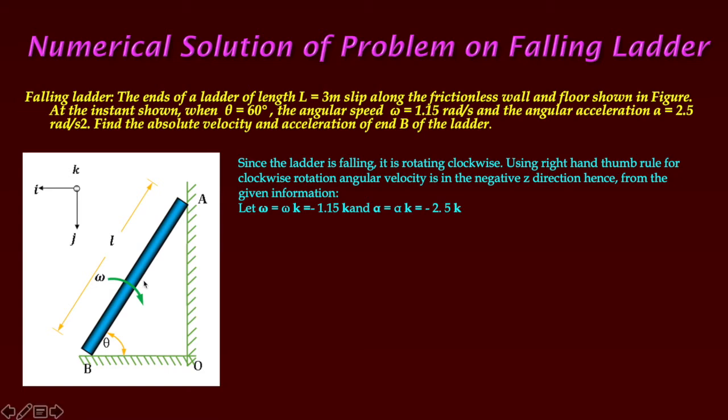What's the direction? We know the direction is perpendicular to the plane of rotation. So what's the plane of rotation? This ij is the plane of rotation. In that case, the direction of omega is perpendicular to ij, meaning in the k direction. So it is omega k, where omega is the magnitude and k is the direction, and this is the angular velocity vector.